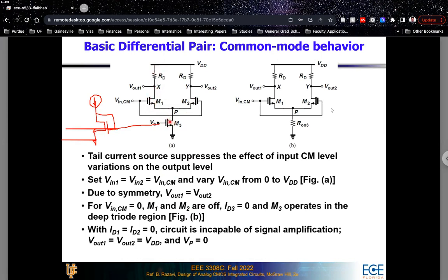Let's just assume that this M3 transistor is on, because you can apply a VGS which is more than the threshold voltage of the M3 transistor, which will mean that this M3 transistor will work as an on switch. If you assume that the transistor works as a switch, then the voltage at the source terminal will be equal to the voltage at the drain terminal, which will mean that the VDS will be very small, or in fact very close to 0.